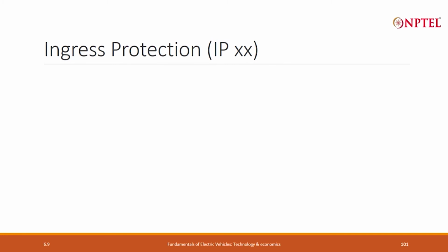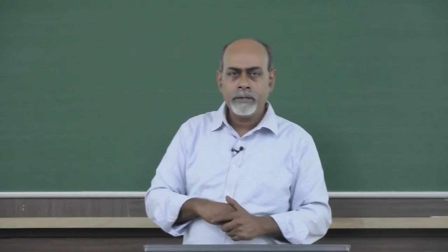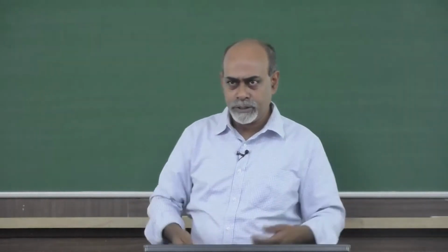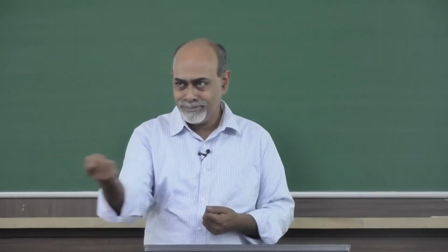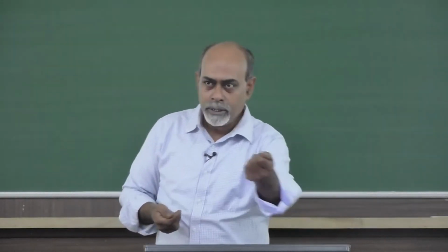And the final topic I will cover now is what is called ingress protection. The motor as well as the controller will be exposed to an environment where there is dust, mud, muddy waters, slush, and rain spray. When I take it to a mechanic for servicing, he is going to apply powerful jets of water on it, and when I am washing at home, maybe I will use a garden hose to clean it. So, it has to be able to withstand all of that.